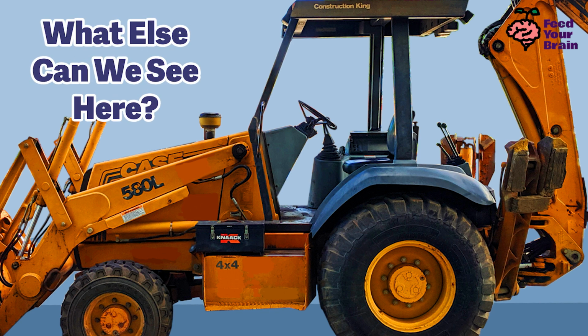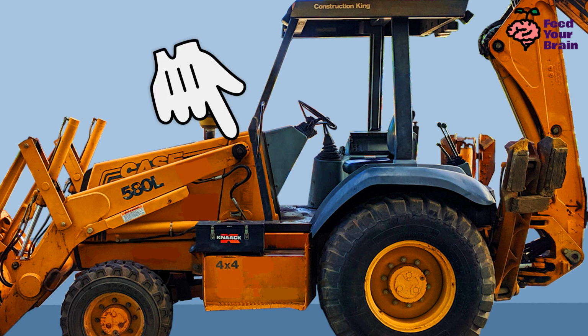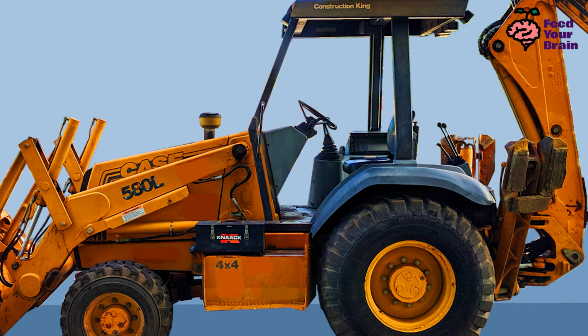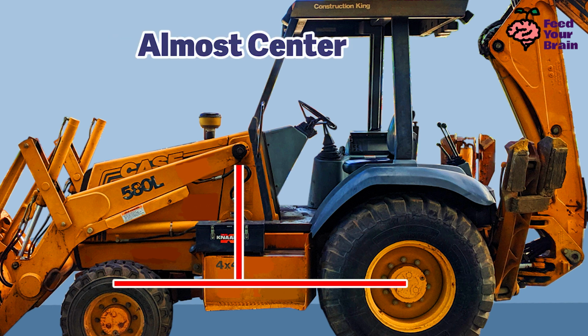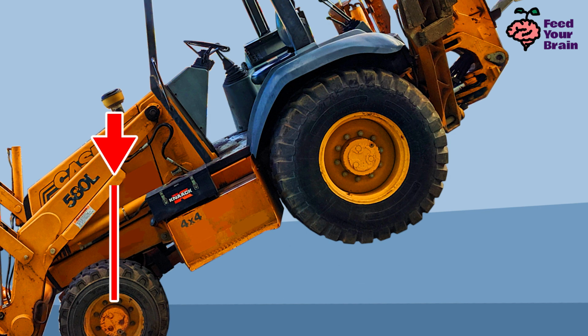What else can we see here? Where is the loader arm anchored to the tractor body? The loader arm is mounted here onto the body of the tractor. Look how far back it is mounted. Do you know why? Because the loader can lift such heavy weight, the heavy weight needs to be put onto the center of the tractor frame, which is about right here. If the loader arm was mounted more in the front, like here, the tractor would tip forward, and that would not be what anyone wants.